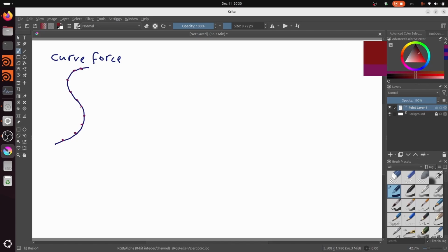So this polyframe node generates, I'm going to choose a different color, it generates a tangential vector along the curve. So the tangential vectors are going to look like this from upwards, downwards along our curve. And we are going to set these vectors as the normals. Okay, so these are going to be our normals. We are going to create normals that are tangential to our curve like this.